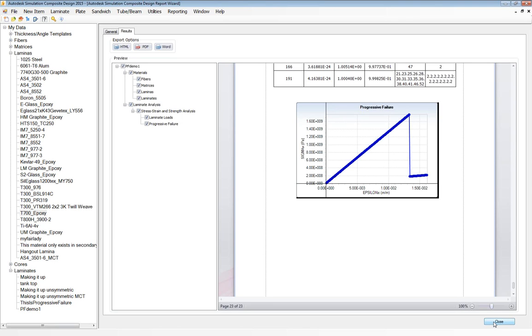There's obviously some limitations. This is for a simple setup where you're just interested in looking at what plies are going to fail. You'd want to use a more complete FEA tool if you're looking at damage progression, delamination, some of those damage zones. If you're looking to capture that level of information, this isn't the tool that's appropriate for that.